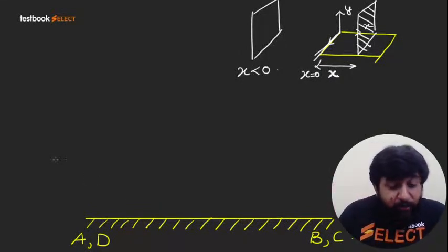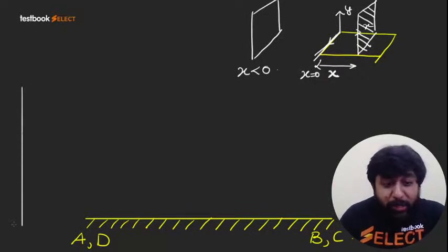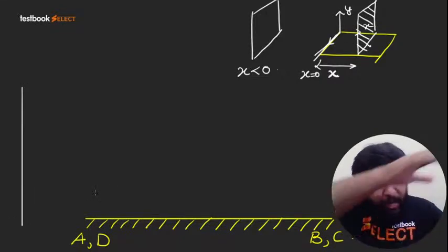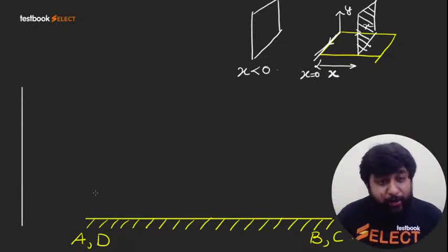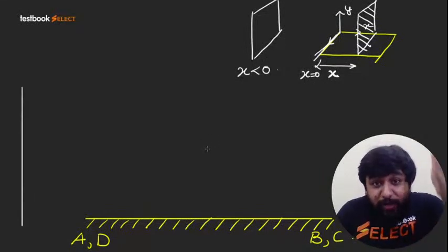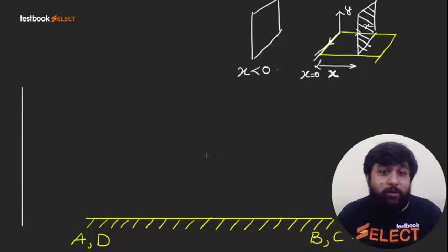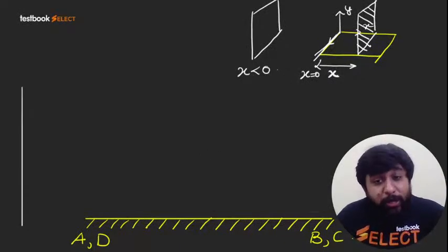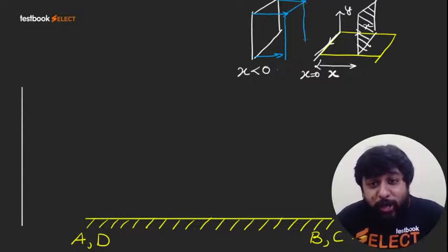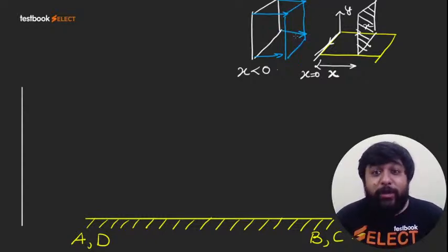So what we have is a cross section which is before the plate. In a 2D figure it will look like this. Actually what we are doing is making an assumption that as water is moving over the plate, before water reaches the plate, the velocity at this cross section is uniform. What do you mean by this? If you take any point on the cross section, the velocity on all the points will be the same.